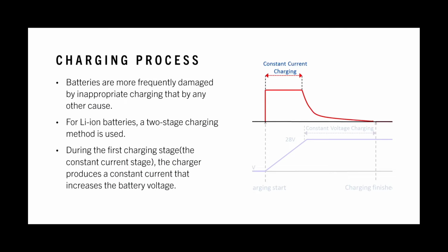In this demonstration video, I will explain how to design a constant current charging and a constant voltage charging method for a controller using MATLAB and Simulink. Batteries are more frequently damaged by inappropriate charging than by any other cause. For lithium-ion batteries, a two-stage charging method is used.